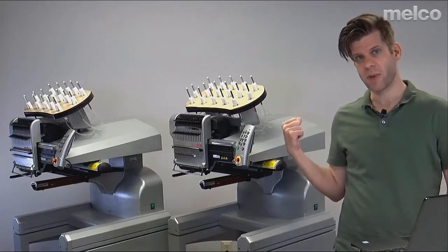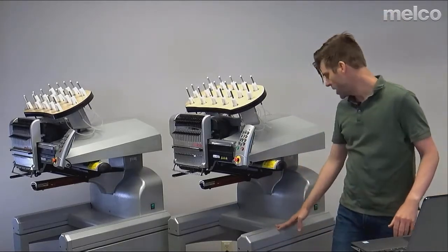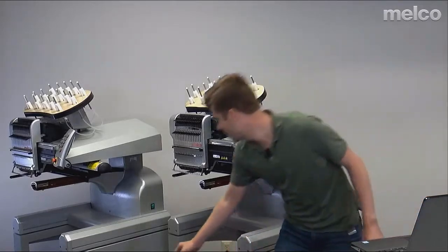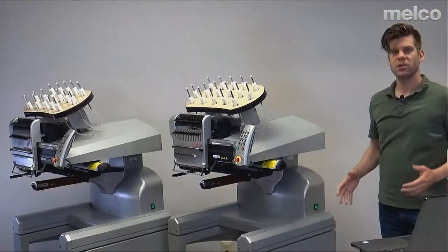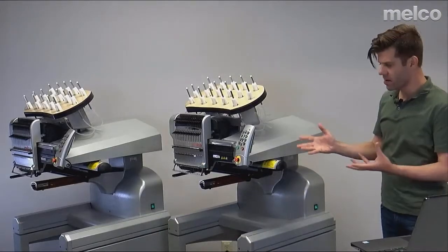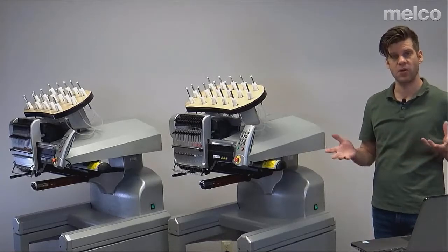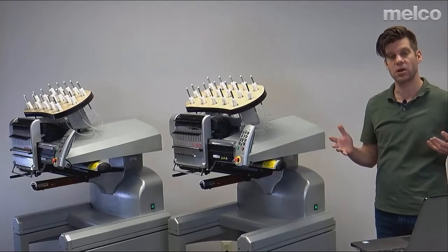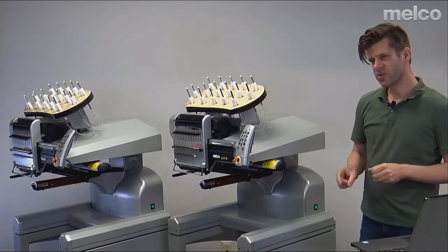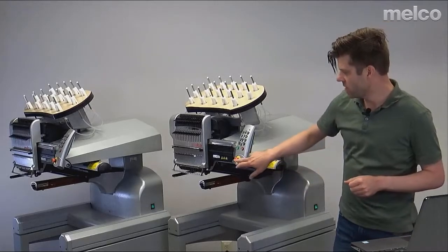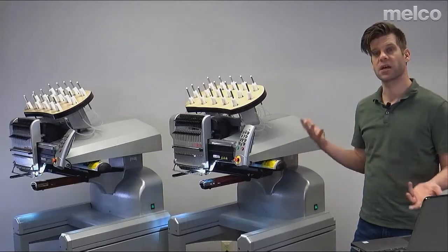Let's go ahead and go back and turn on the machines. I've got multiple machines here right now. I'm going to flip the power on this machine, and then flip the power on this machine. As these machines power up, the lights will come on and they'll move, doing a little home dance to make sure that all the parts of the machine are safe and ready to completely power up. If you notice they don't do that, check and make sure that your e-stop is disengaged. If the e-stop is engaged, it's not going to be able to fully power up.